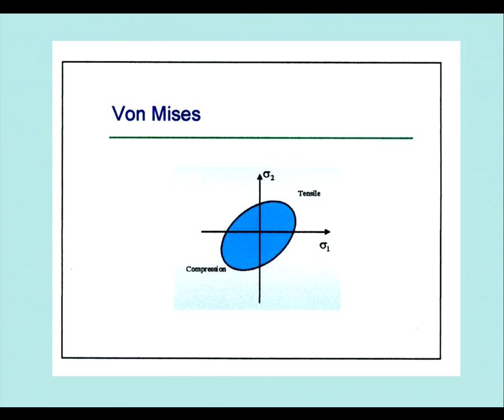So, if I take this stress up to here as a hoop stress, and I've got nothing else other than pressure, then I can end up with a point there where that is sigma hoop times Poisson's ratio, and this is sigma hoop.